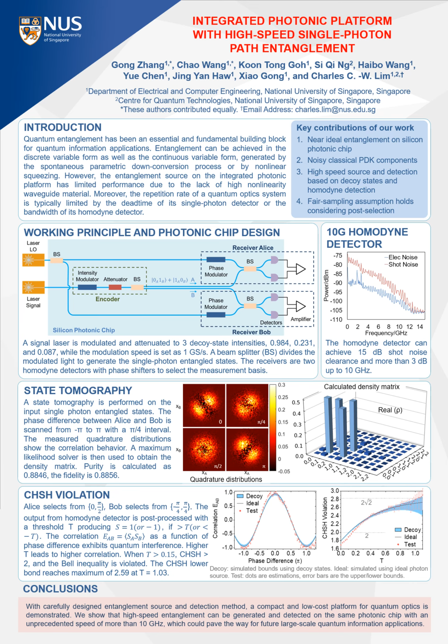However, there are still some limitations when preparing entangled states on chip. The nonlinearity for common photonic platforms is not high enough. As an example, the silicon or silicon nitride platform is the most common one, but they lack second-order nonlinearity. For lithium niobate or aluminum nitride, the fabrication is much harder and it's typically not available in large foundries. And the repetition rate is another issue for chip, which is typically limited by the dead time of single photon detectors and the limited bandwidth of homodyne detectors.